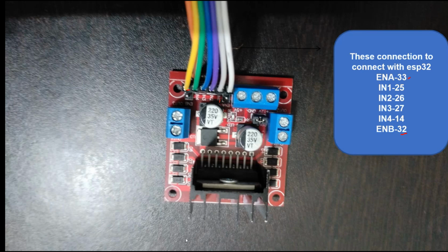Okay, and then give that connection to the left motor. Okay, so you can see the left connection where the black, this is black. Okay, black wire, and this one is red wire. So I am representing as B and R. So this is for the other motor or connection. So this is where we have to connect two things. So we have 3 terminals here. We have ENA, input 1, input 2, and then IN3, IN4, ENB. It is there. So just give the connection and then give it to the pins.